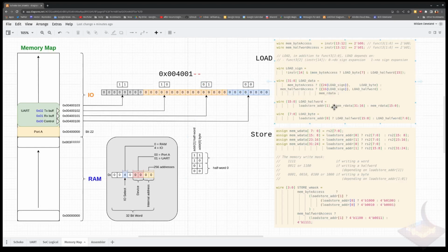They're determining which piece of the 32-bit word we're going to pull from. So for a half word, you're either pulling from the entire low 16 bits or the entire upper 16 bits. If we're doing load bytes or store bytes, doesn't matter, we're just looking at the load right now, then we'll look at only the lower byte or the upper byte of the half word itself. So you can see that we're cutting space in half as we move down this tree.